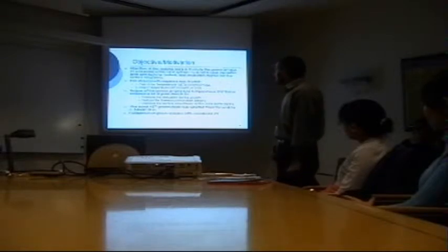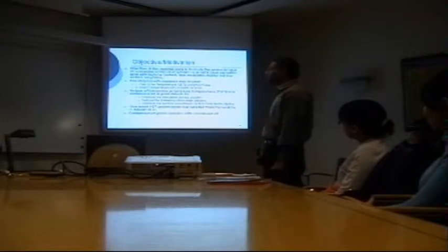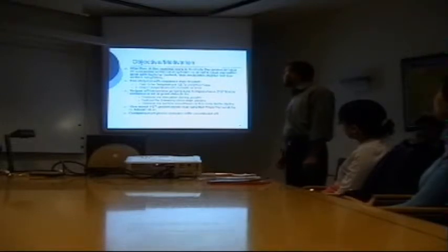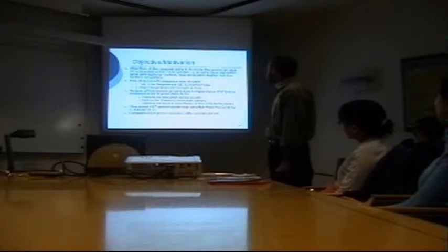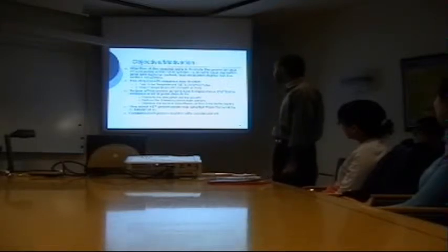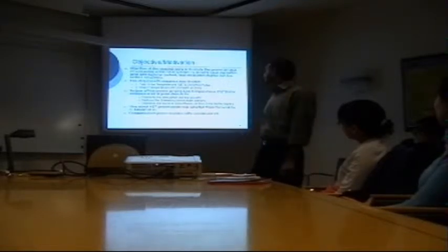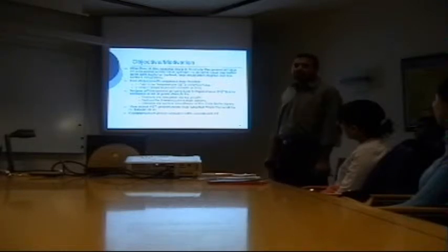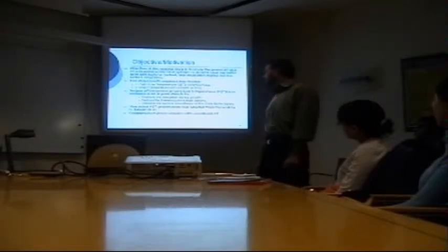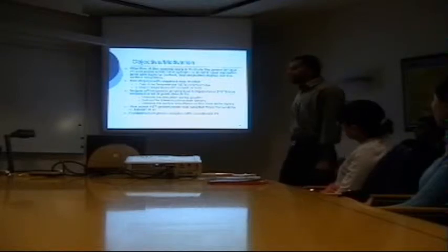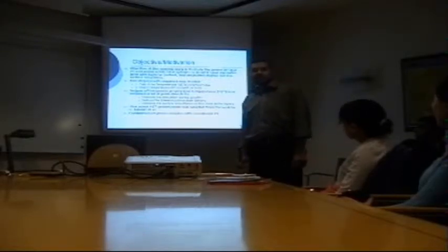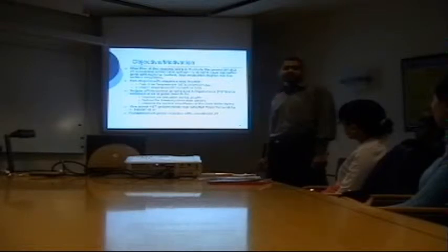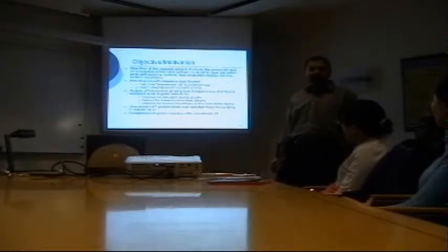So the objective of this diploma work is to study the growth of silicon germanium virtual substrates containing a thin silicon germanium epilayer, to achieve a silicon germanium top buffer layer with high germanium content, high relaxation degree, and low surface roughness. To grow these virtual substrates, we use a two-step growth scheme. In the first step, the silicon germanium layer was grown at very low temperature, and in the second step, the silicon germanium layer was grown at very high temperature.